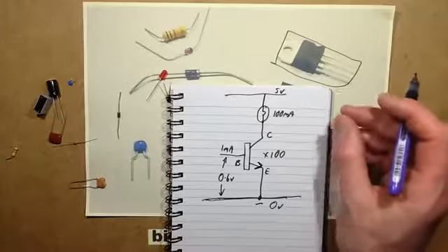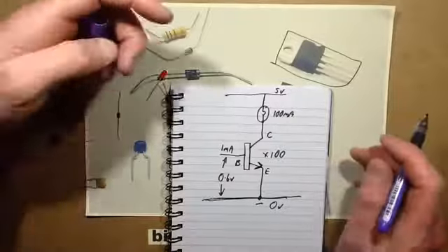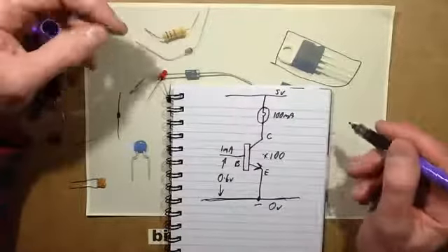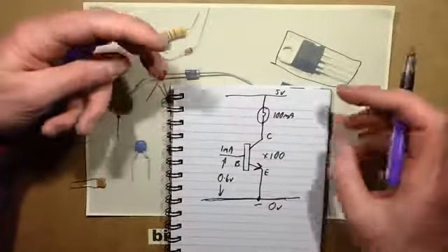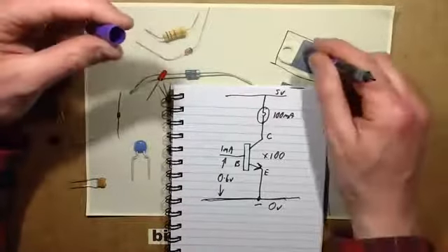You can use it to switch quite a modest current without even applying a heatsink, because traditional transistors would have a slight voltage drop across them, resulting in heat dissipating. So MOSFETs are much better for that.